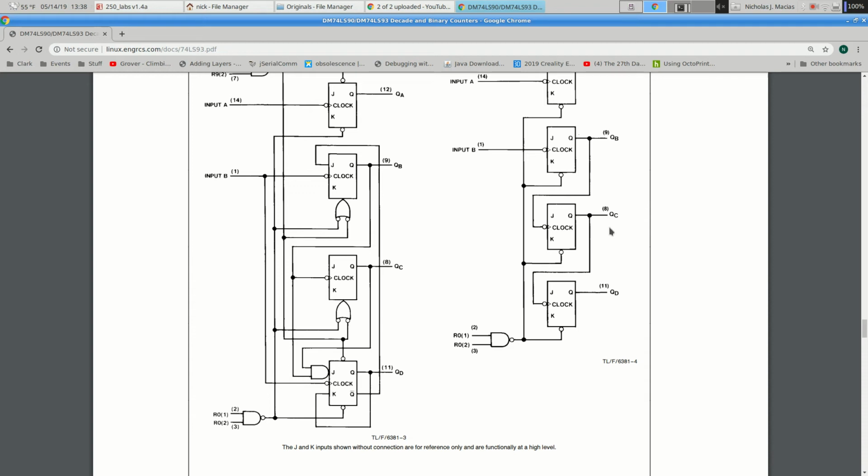If they're not, don't bother with the 74138 yet. Right? You're going to be feeding in a signal that's not doing the right thing, so the output's not going to be doing the right thing. So play around with the timer and the counter and get this output to be nice and clean, exactly what you expect. All LEDs off, first LED on, second one on, first one off, both on, and so forth. And then when that's working, hook that up to the 74138 and see if you can get the whole sequence of LEDs to count. Does that make sense?